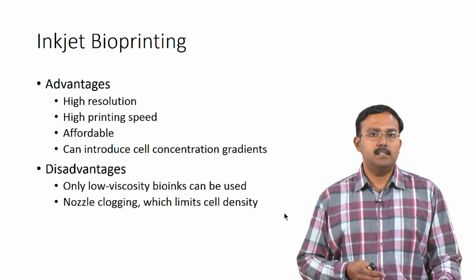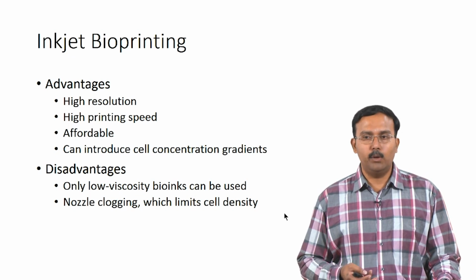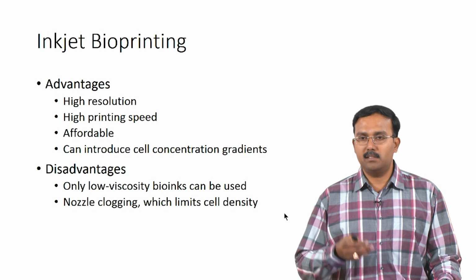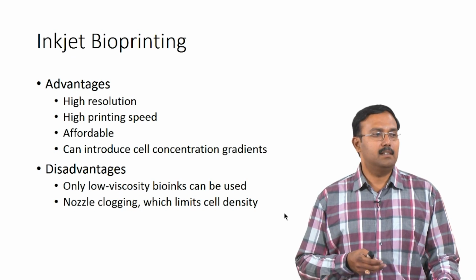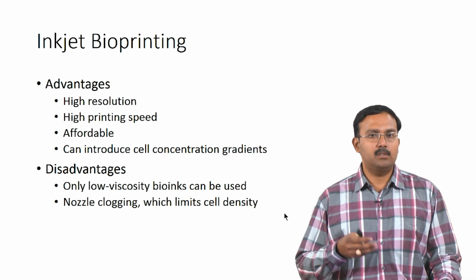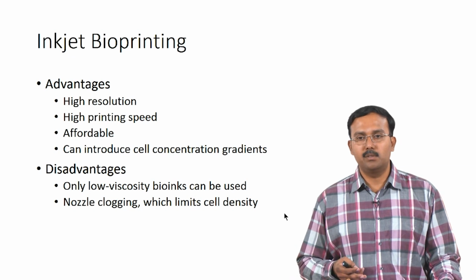The disadvantage is it can only use low viscous bioinks. If you use highly viscous bioinks, it is going to clog the nozzle, and clogging of nozzle can also limit the cell density which you can use.